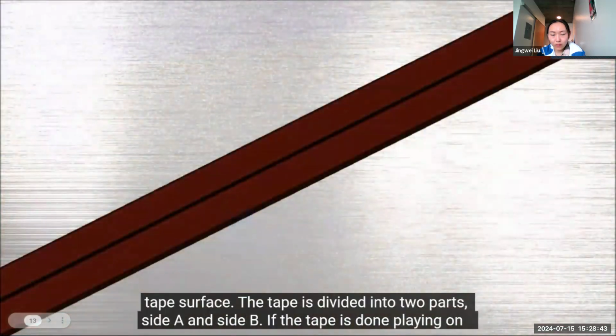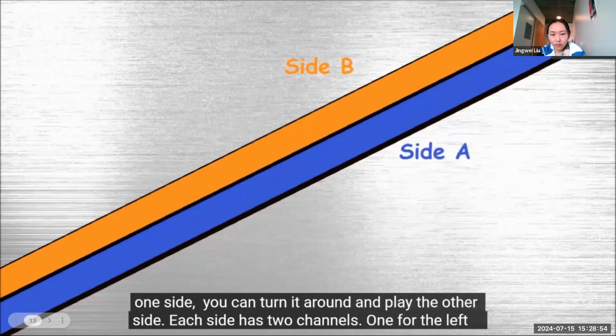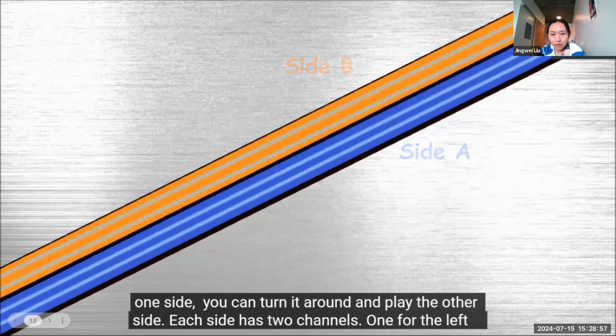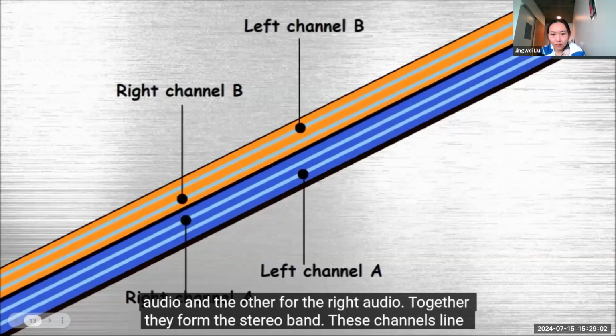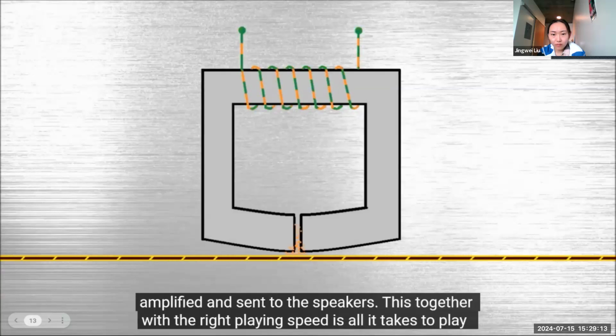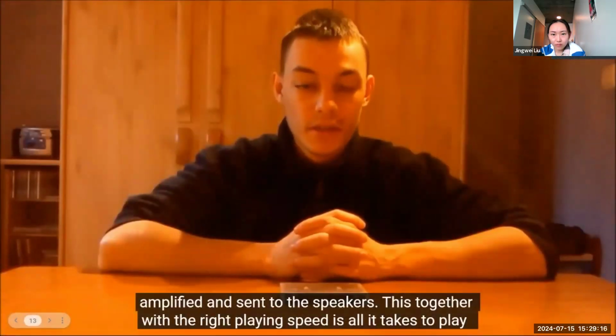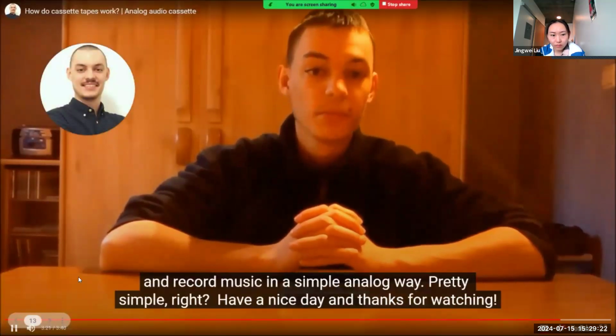Let's take a look at the tape surface. The tape is divided into two parts, side A and side B. If the tape is done playing on one side, you can turn it around and play the other side. Each side has two channels, one for the left audio and the other for the right audio. Together they form the stereo band. These channels line up with the stereo head and the magnetic signal is converted to a small electrical signal. This is amplified and sent to the speakers. This, together with the right playing speed, is all it takes to play and record music in a simple analog way.